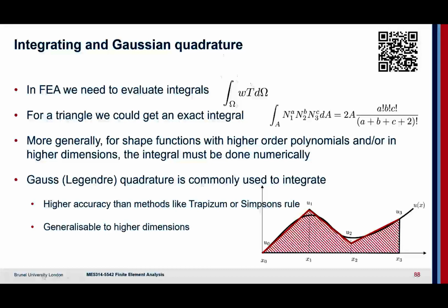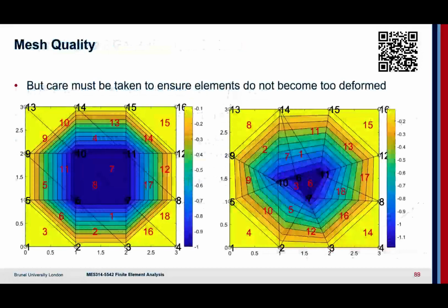This process, if you wanted to do a finite element solver for more complicated functions, you would essentially just replace this expression here with a Gaussian quadrature of arbitrary order, and that would give you the way of integrating. But otherwise, the process is very, very similar to what you've seen.